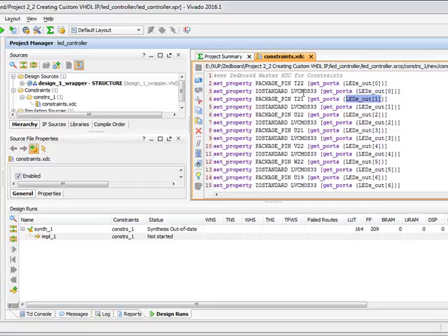I think T22, T21, and you can also see the location of these pins on your ZedBoard. T22 is, I think, the left LED, and the other is the right LED, U14. So these are the LEDs. Let's close this constraint.